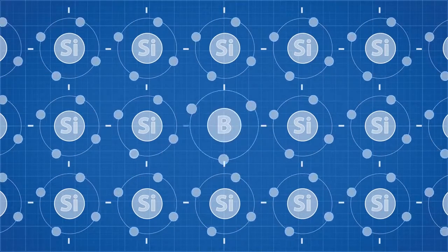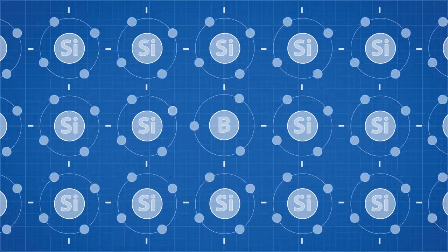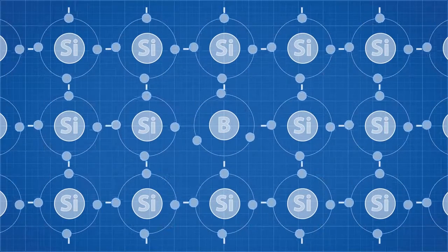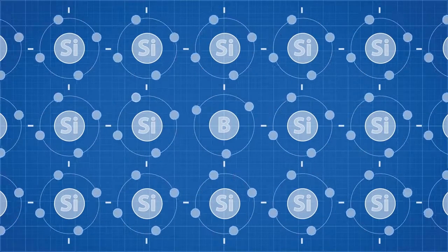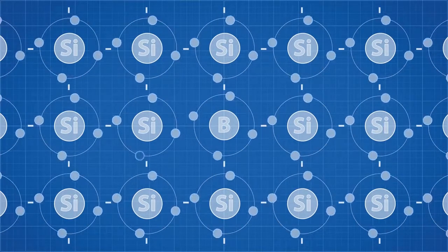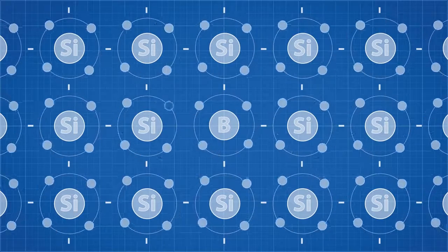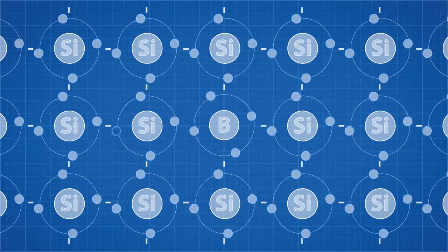The p-type is positively charged because it is doped with boron, which has 3 electrons in its valence shell. This structure wants to gain its final electron, and will steal electrons from its neighbouring atoms. This creates a mobile positive charge, called a hole. The conductivity of the material has thus been increased, as we've increased the number of mobile charges.